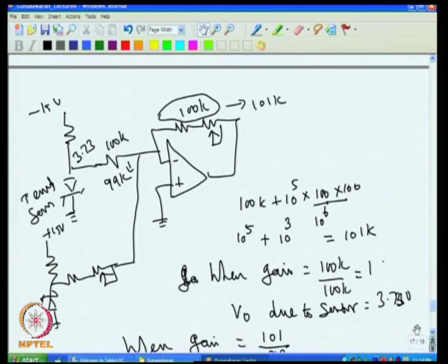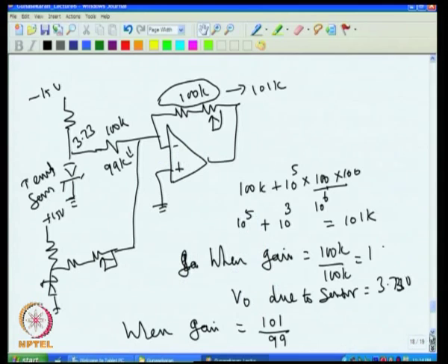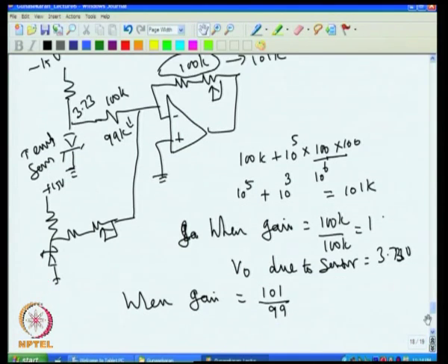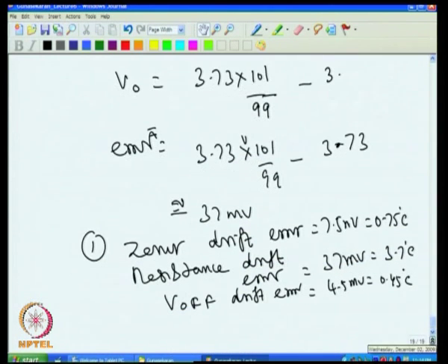By now you would have understood that in analog circuit design the components play a significant role. If we take any analog circuit, you will find plenty of resistors and capacitors, and one should not think that only the value is important, and that the drift of these resistors and capacitors is not important. One should not take that view. They are very important and one should consider them.